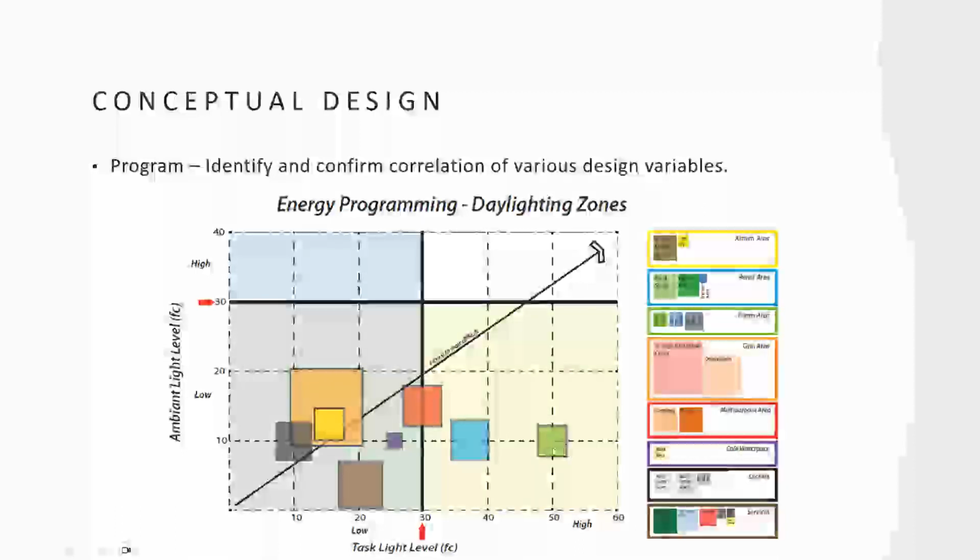Okay, so like this space, the admin area, requires 50-foot candles. We're currently getting between 5 and 15, it looks like, somewhere in that range. Okay, so not really good. But for our bigger areas, like the gym area, low amount of foot candle requirements, fits in our range. Okay, we should invest in daylighting for this space, but not necessarily this one. Or depending on if, say, all these spaces are viable to be daylit, but we weren't planning on it and we were planning on doing these. Okay, now we need to go back and rethink our design and basically try to get the inverse to happen.